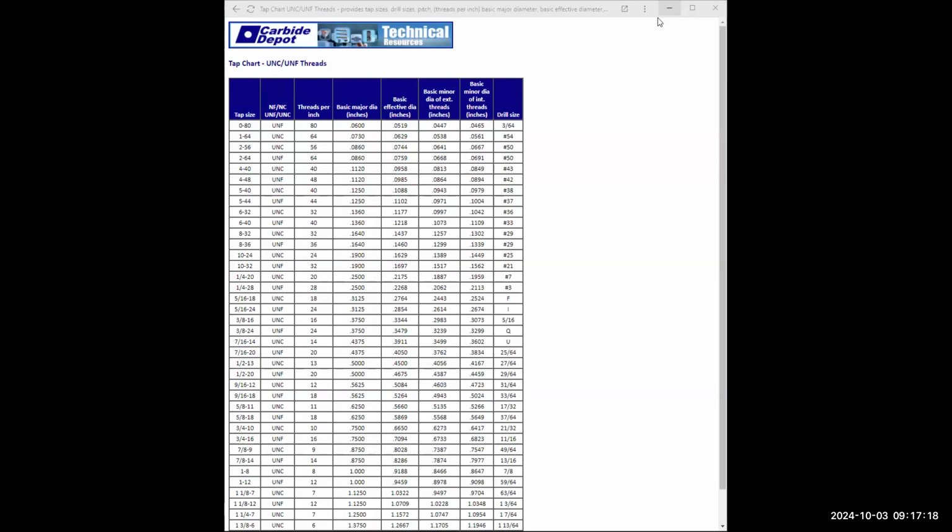Let me show you how to do that again. I went kind of fast, I'm sorry. Type in CP for copy, enter. Click on the text you want to copy, click, enter. Indicate anywhere on the screen, click, drag it down, click, enter. Now type in DD edit,